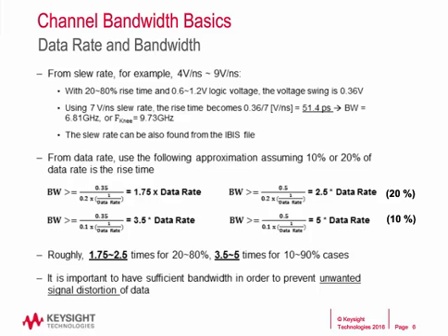Again, this is not an exact formula for the bandwidth, but it can provide a useful guideline to determine a good bandwidth for signals and channels with as little distortion as possible. I typically use the 2x rule for the bandwidth calculation from the data rate.